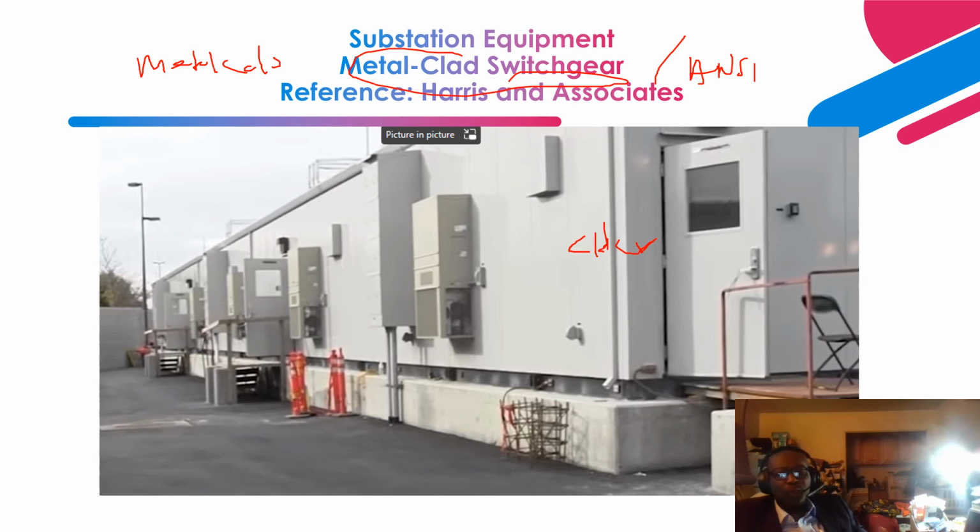So that is the difference between metal clad switchgear and metal enclosed switchgear, right? In metal enclosed switchgear, you see that some of the live parts are exposed and it is not compartmentalized. But in metal clad switchgear, you see that most of the live buses are basically insulated. It's more for safety and basically protecting our personnel. And also, as you can see, the cladding nature of the external, peripheral.